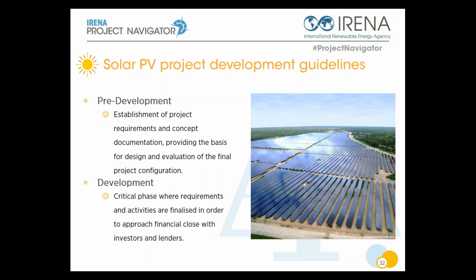So during assessment, we have a gross evaluation of both solar resource and of course yield. But here you need to understand, okay, can I generate an hourly power production value based on a P50 resource analysis? Because those are the questions that technical consulting engineers will ask when they represent banks or investors.